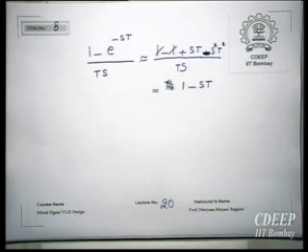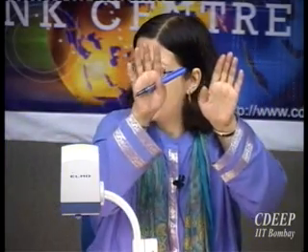What he says is that because sT is small, in fact, the effect on phase will be more than the effect on amplitude. But it will have, if you remember in the sampling part, this effect is what is called the sinc function. Therefore, at very low frequencies, it will be almost 1. But as frequency increases, it will even attenuate the amplitude.